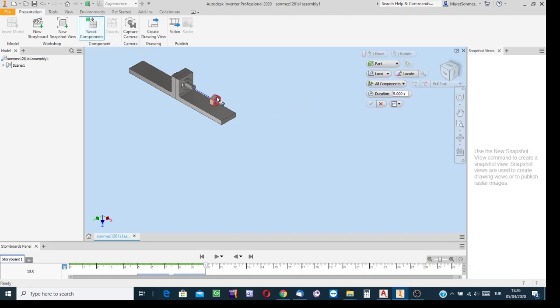Continue. Hold this component, select the component option from this list, indicate the nut, and then continue. Hold this arrow, and this is to say that as if there is a robot, and the robot hand is to displace the nut in this direction. And then click on this arrow and move the nut in this direction. Consider that there is a basket to collect the nuts, and over there is a basket.